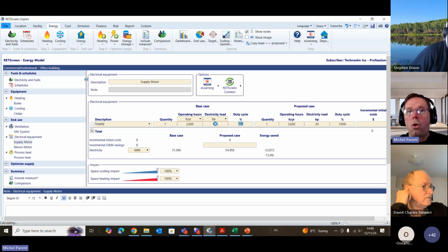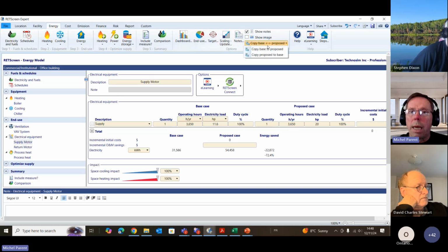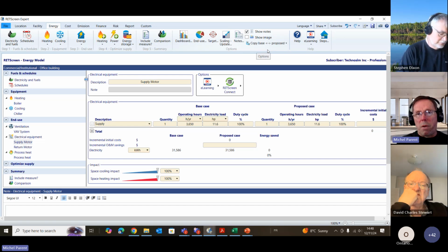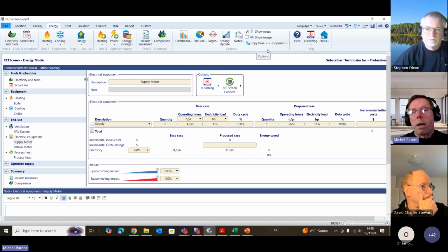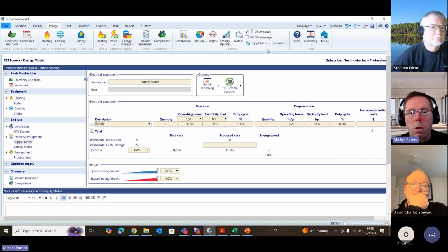Quite important to take into account what we call the affinity law. When you have a drive, don't multiply the drive percentage by the brake horsepower or by the kilowatt, unless you can read the kilowatt on the drive, then you use that. But if you have the motor horsepower or the brake horsepower, you will multiply by the speed, exponent to the cube, or if you're conservative, exponent 2.7.